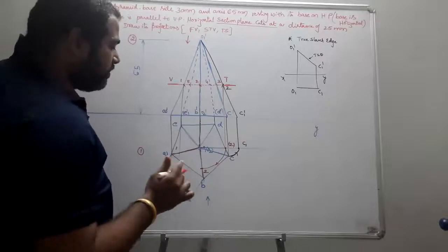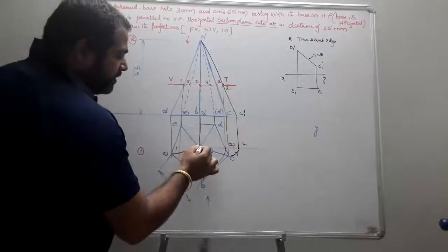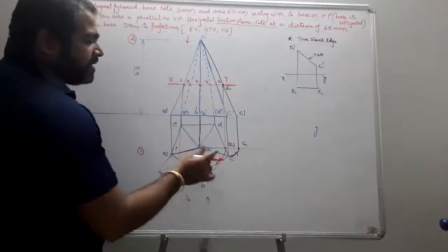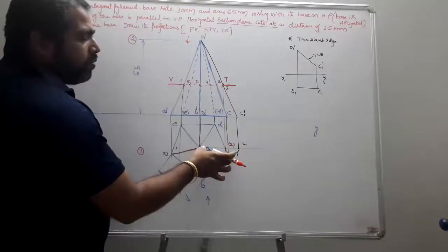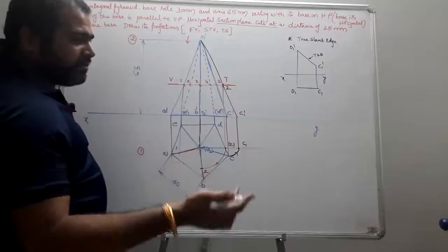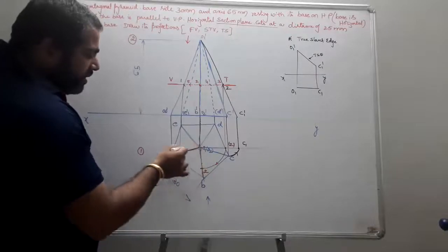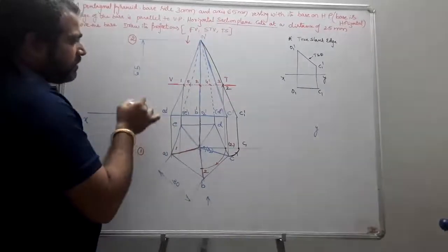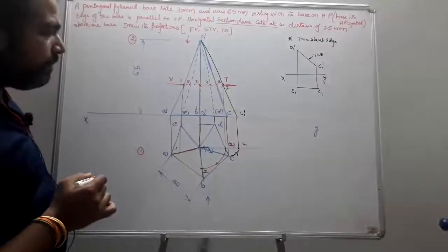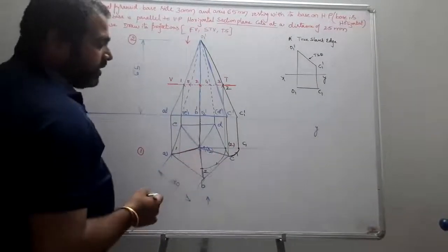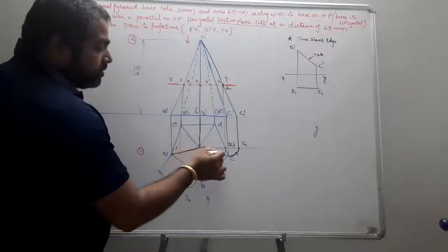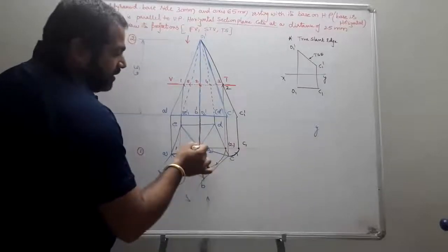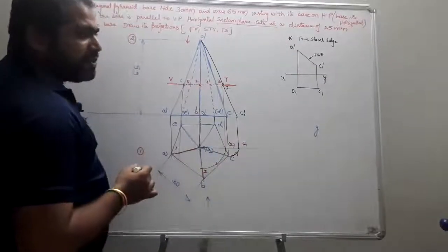How is it possible? Simply from O, I draw the line parallel to XY. I create my OC1 as your new true slant edge for reference. Or you can take it this way, OA is also rotated and comes like this. O as center, OC as radius, draw an arc up to the horizontal line which I drew parallel to XY.